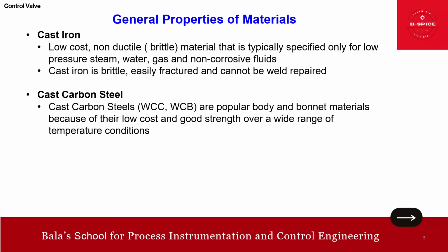Okay. Then we have WCC. What is this WCC? Again, it's a carbon steel grade, covered by the ASTM A216 standard. WCC is a standard substitute for the WCB.